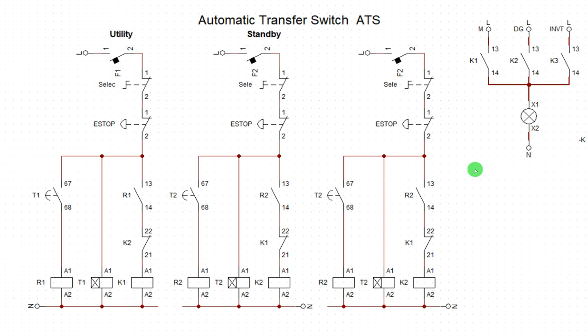please listen to this voice note. I said, I want you to leave this logic the way it is with the rest of the logic. Don't alter the timer. Don't subtract anything. Leave it the way it is. Because in future, when the inverter goes bad and the end user is not able to replace or fix the inverter, he might decide to bring in Gen 2, maybe a smaller gen, to alternate this other gen. So because of that, the ATS will also be alternating that second gen.